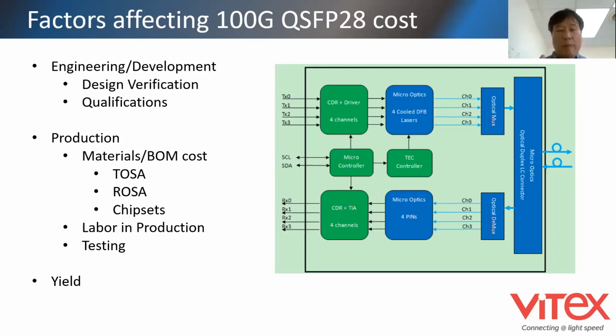These days, this is all packaged. So we call it the transmitter optical subassembly, TOSA. That's the one that contains your lasers, and ROSA is the one on the detector that contains the photodiodes. These are the main parts that make up the transceivers: optics, TOSA, ROSA, and especially